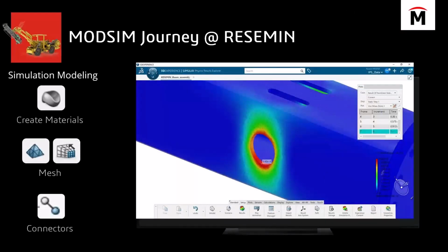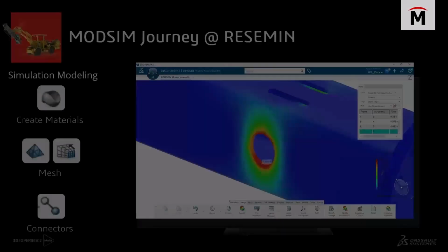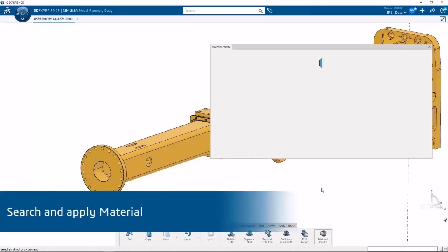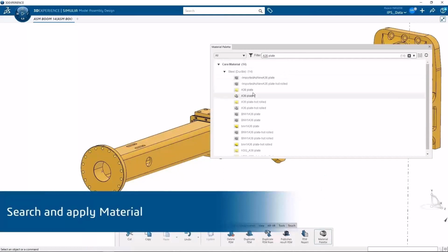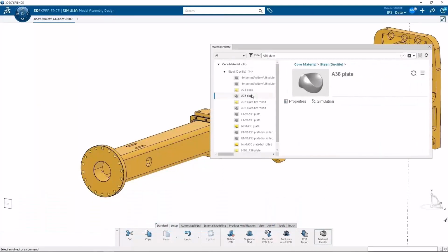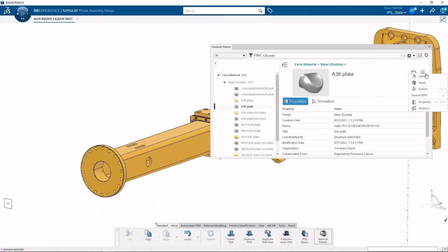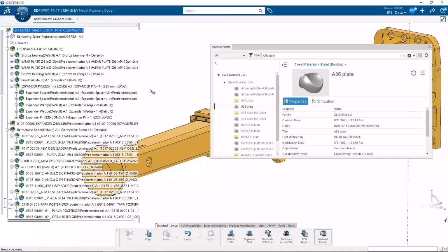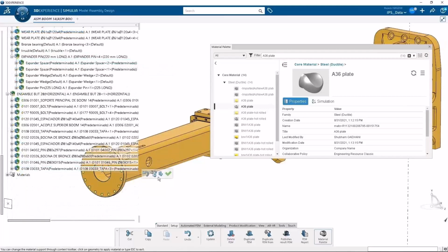So while the finite element representation, or the FEMREP, is not something we usually use in SOLIDWORKS, the steps are pretty similar here, and there's an assistant panel that can walk you through it, similar to the study advisor you find in SOLIDWORKS. Now we are going to use a different material library over on the Simulia side, and this library is much more extensive than what you're going to find inside of SOLIDWORKS. For instance, on the fatigue side, you're going to be able to get SN curves a lot easier here.